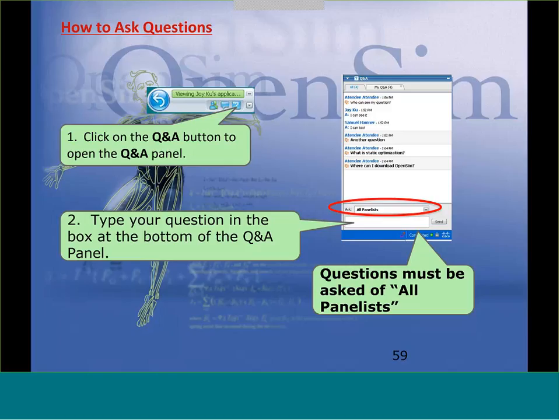So when we converted our joint loads from OpenSim into the finite element simulations, we made sure that the local coordinate system of the knee joint in OpenSim was located and oriented the same way as the coordinate system in our finite element simulations, so that we were consistent.